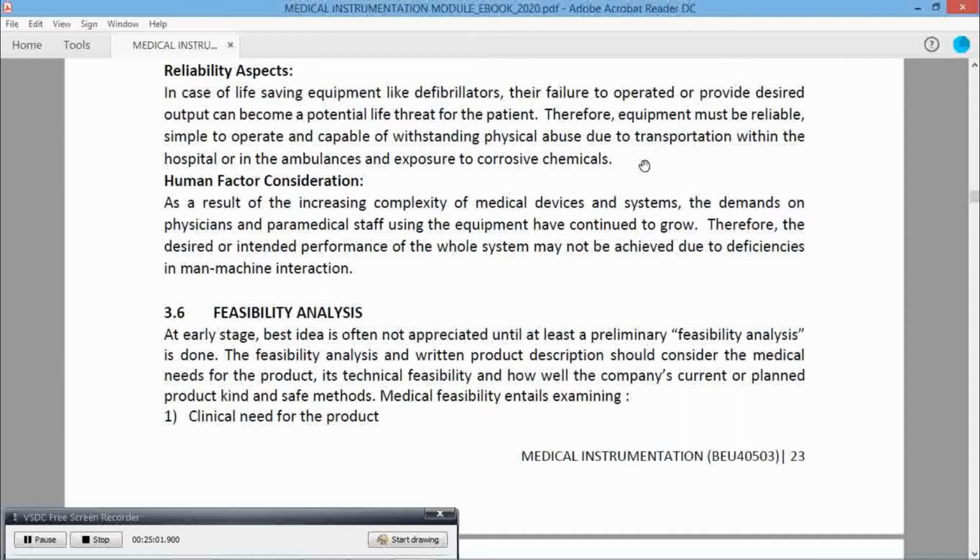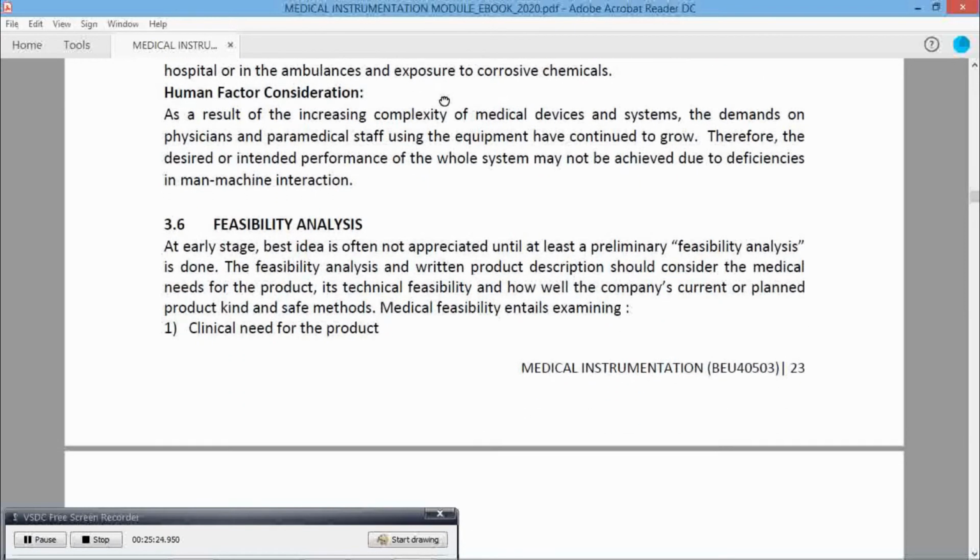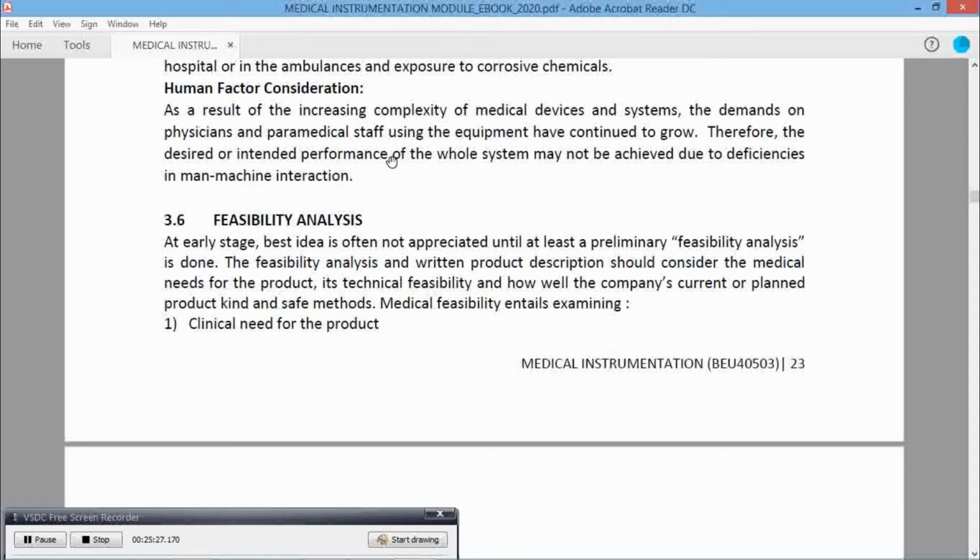For example, you've been testing the equipment in your hostel, where the room doesn't have much light, but when you come to UTHM, it's an open area, so you have much more light, so it actually interferes with the sensors, with the system, so that the system becomes not reliable. So you have to have this in your mind when you do this design.